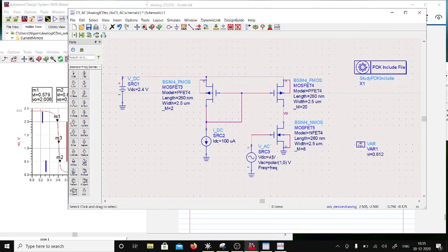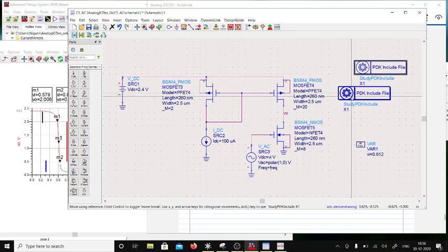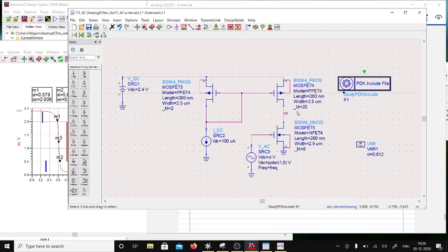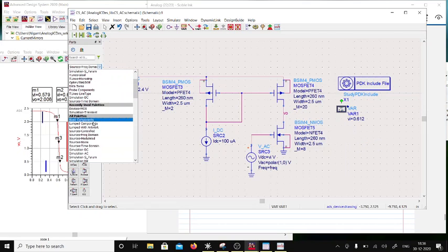So I am having Vi as the DC voltage, and then I am swinging 1 volt at the input. Because it's an AC simulation, it's okay. So output can be around 1000 volts, right? Irrespective of supply. Then I will be able to get the gain. Okay. So now I'm going to do here AC analysis. Simulation AC.